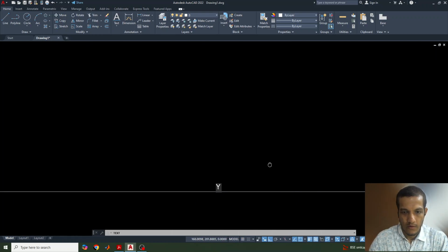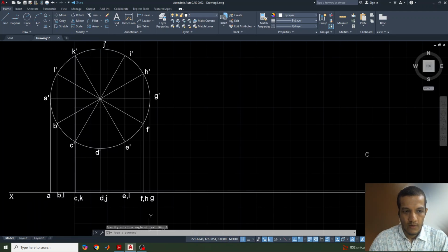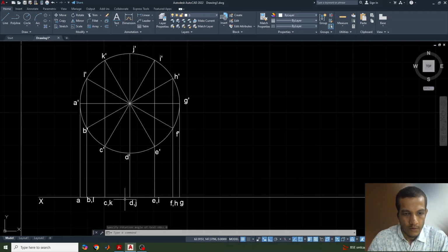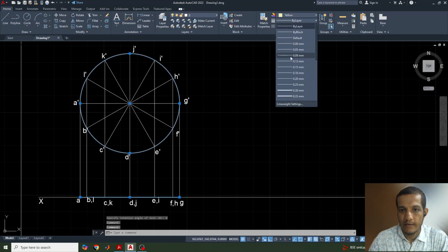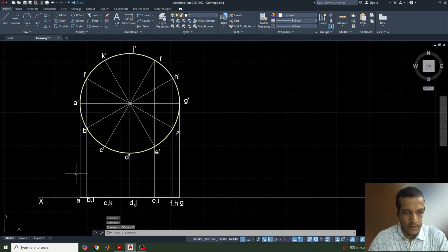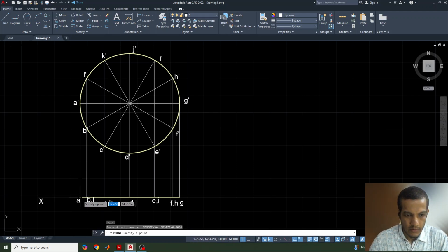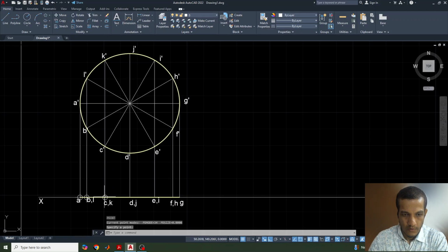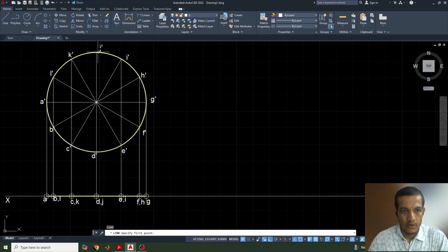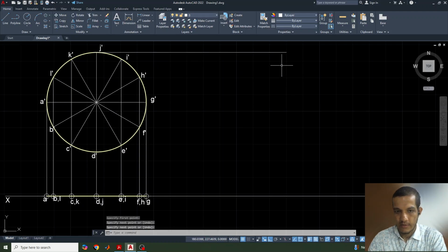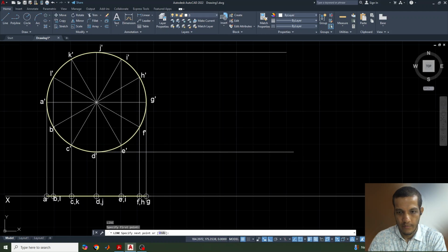Okay, now the top view and front view, we just highlight this with a different color and increase the thickness of that, and meanwhile we'll give some point locations for all this. It will be easy to draw in the next step, because the next step is the given ellipse shape that needs to be drawn, so let's draw this, projecting this line from there and from here.